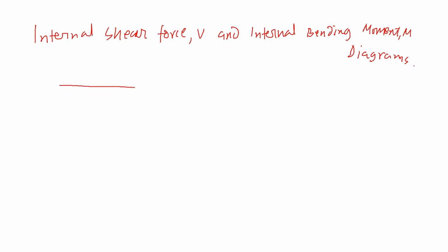Imagine that we have a beam that is simply supported like that. You have a knife edge contact here, and then a rolling contact here, and then a load in the middle of this piece. Typically we express load by using P. So this is the situation, this is the problem. Now step number one to solve, we want to see what's going on inside this piece in terms of shear force and bending moment. And if we know that, then we'll be able to tell whether this thing will fail or not. So step number one is